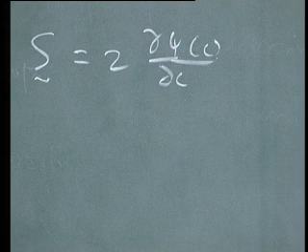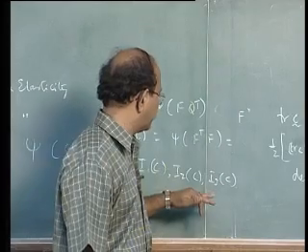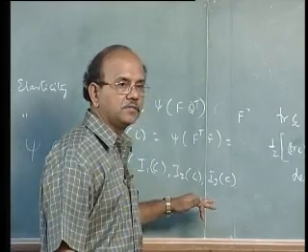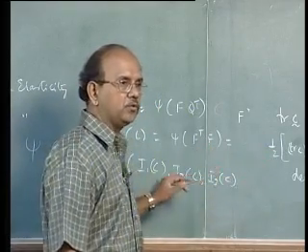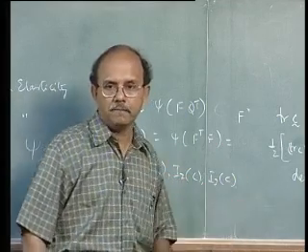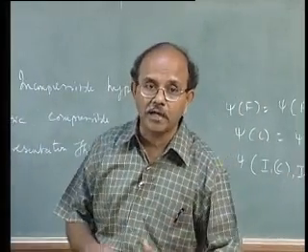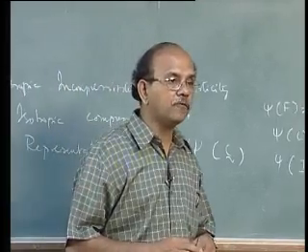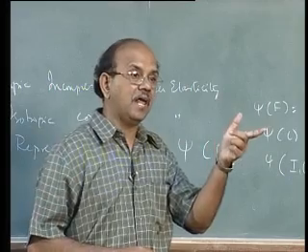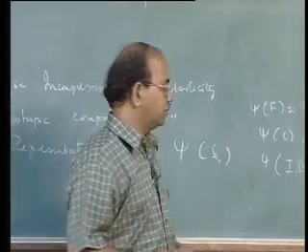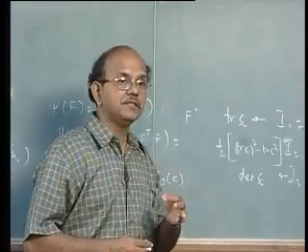Note that this equation is written in the reference configuration. Since the eigenvalues happen to be the same, whether I use C or whether I use B, this whole equation can again be written in terms of B as well. That is where F is on the left of F transpose, that is in the spatial coordinates.